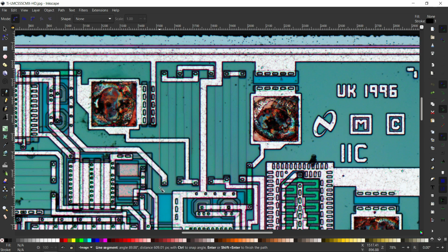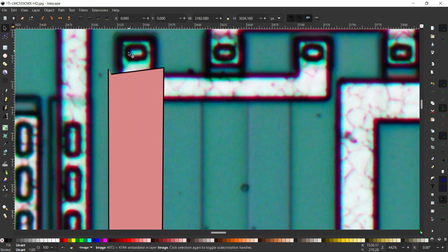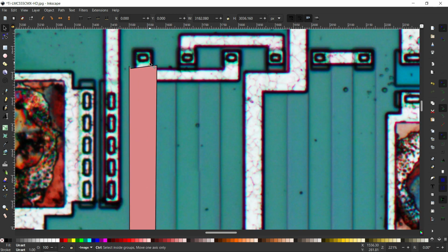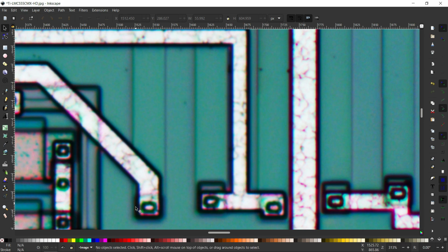So here whatever you are seeing, the square boxes, this is a complete device. Okay, see this block diagram, let me highlight with some additional colors here. First I will select, then I will highlight some color. See here, this portion is a resistor, because on top of that they have a contact. If you take a closer look, these are via contacts, and at the bottom also they have some additional via contacts. I think I have routed something here, so that's why you may not be able to see this. Okay, let me delete this. So here hopefully you can see some via structure.